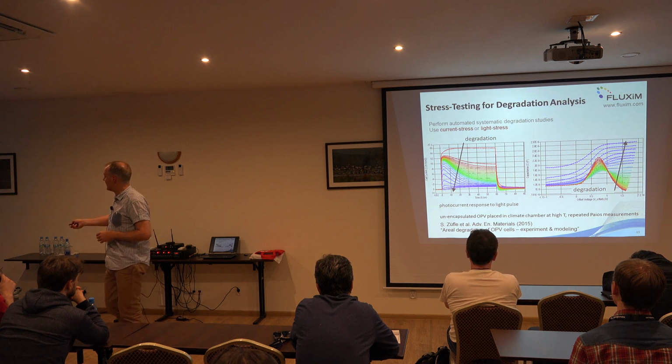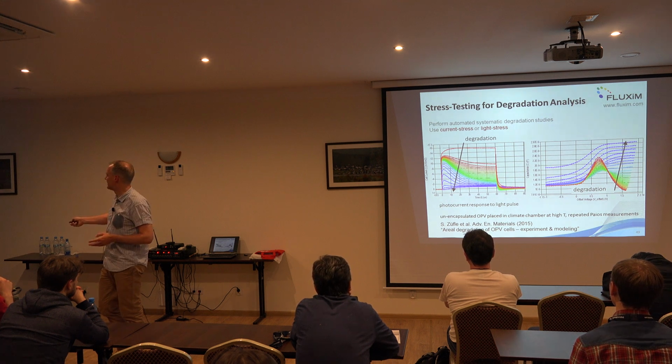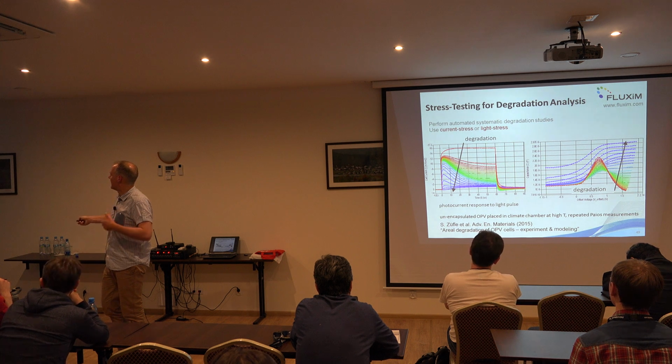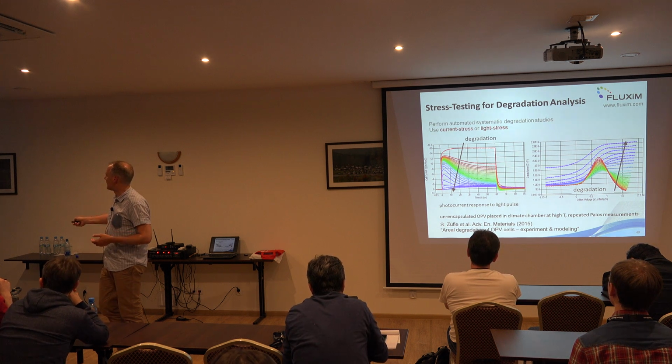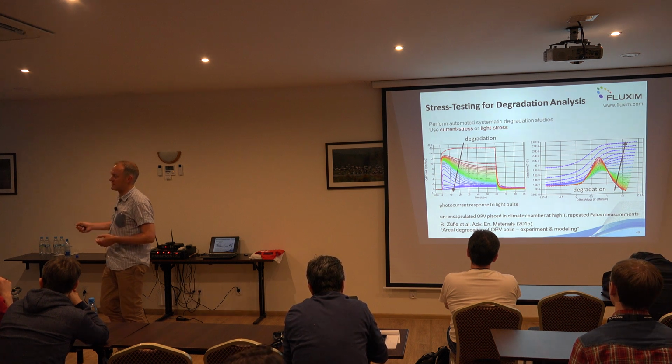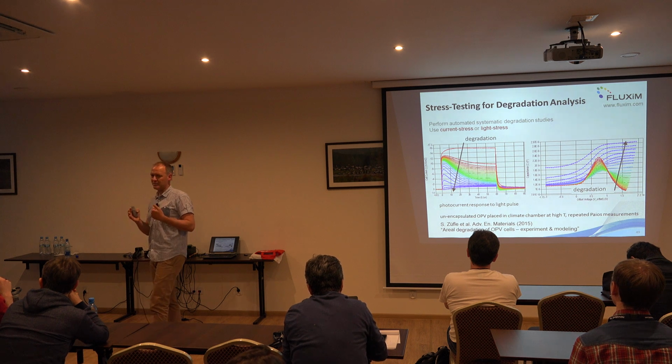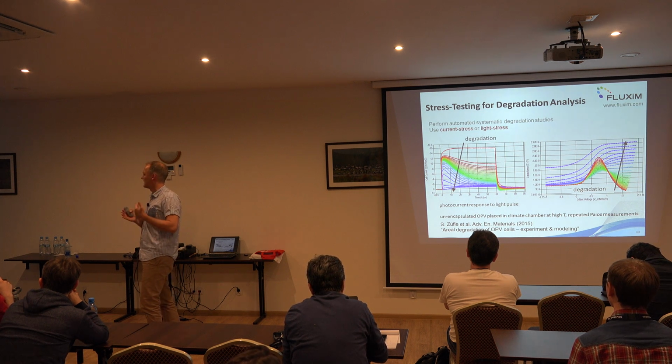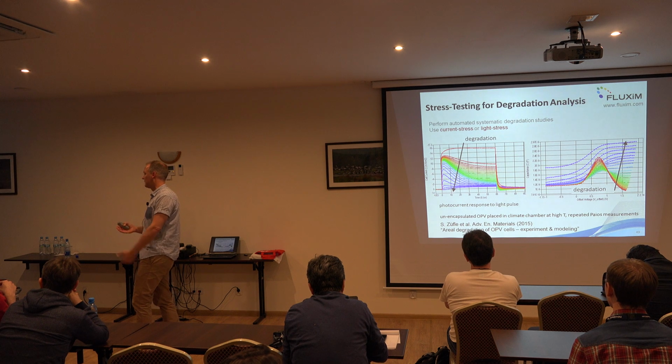We see the red curve is the typical capacitance voltage curve of any organic semiconductor device. We have a CV peak in the fresh state, but then during degradation, something strange is happening. At the end, we have a very high capacitance here, and even a constant capacitance. So somehow there's a blocking behavior. There are charges injected, but they cannot penetrate further.